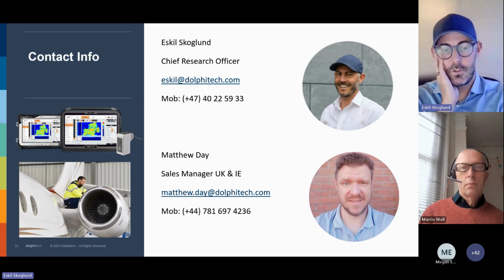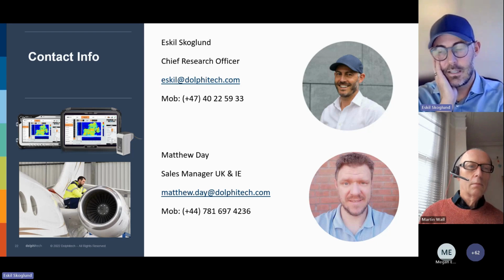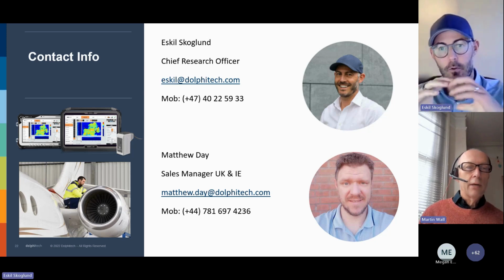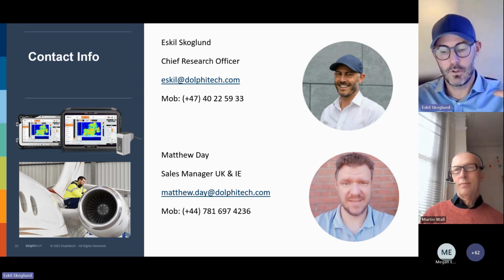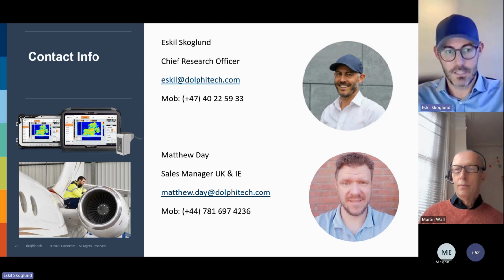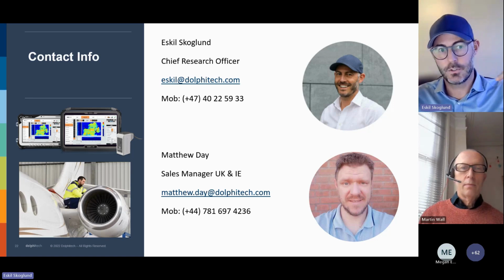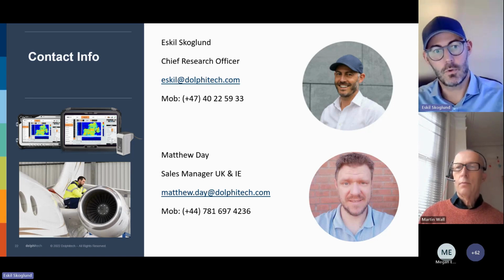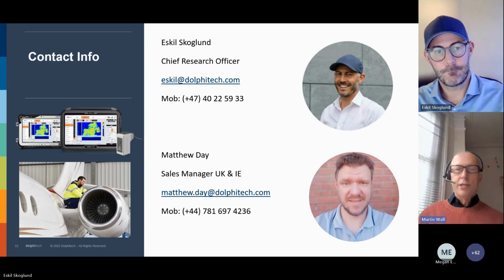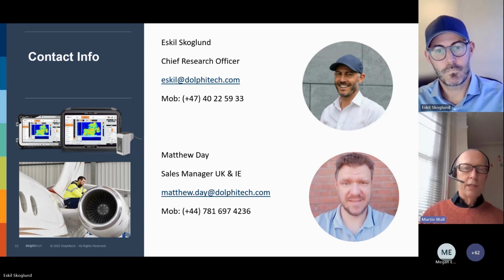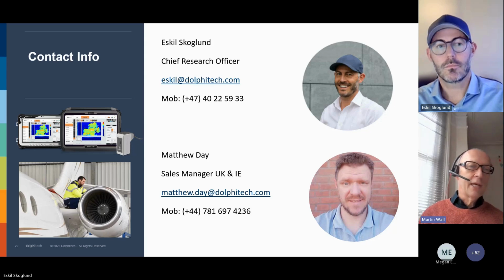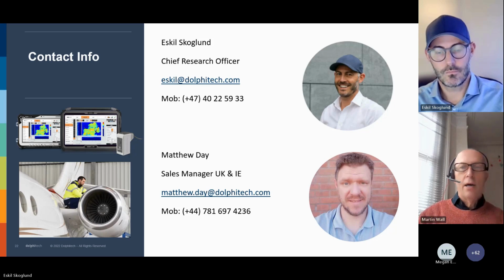You don't have to use all the data, but you can use statistics like I showed you on corrosion. Yes, and of course, it's compatible with scanners, large scanners like pipe scanners and stuff like that. We have XY encoders, so you can plug it in and it works seamlessly. Yes, corrosion is an interesting one because you're looking through thickness for indication of corrosion pits, and in composites, one of the key elements you're looking for is delaminations, which is again a similar sort of C-scan through thickness.